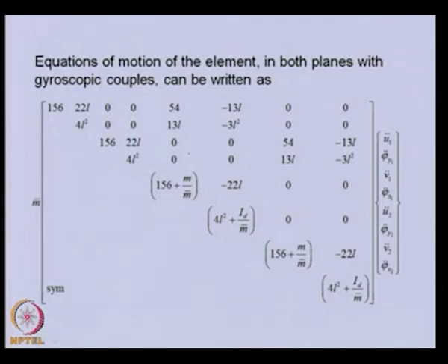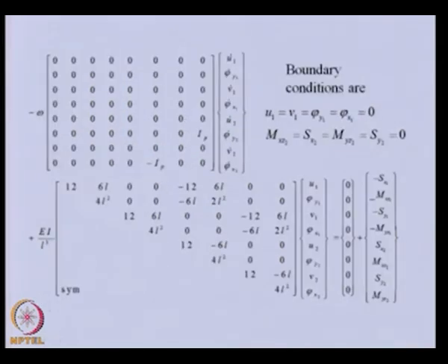Now, the similar thing will be there here. This is the gyroscopic matrix which we have taken from the dynamic approach, because now the order of stacking is the same as the finite element formulation. So, this we can directly plug in. This is the stiffness matrix. So, the 2 plane motion elemental equation we have now assembled in this form. Depending upon the order of these field variables, the relative positions of the stiffness matrix terms will change.